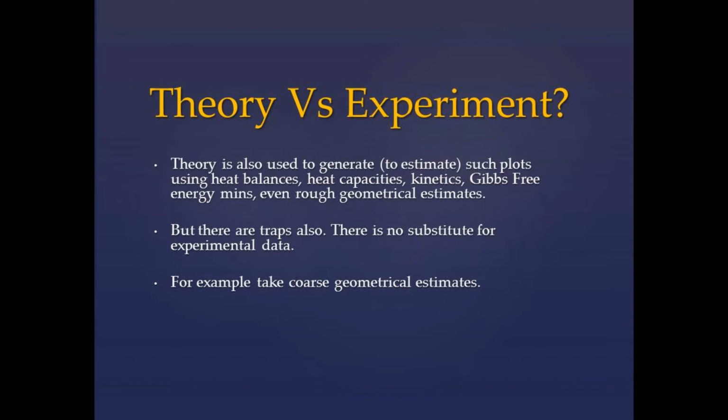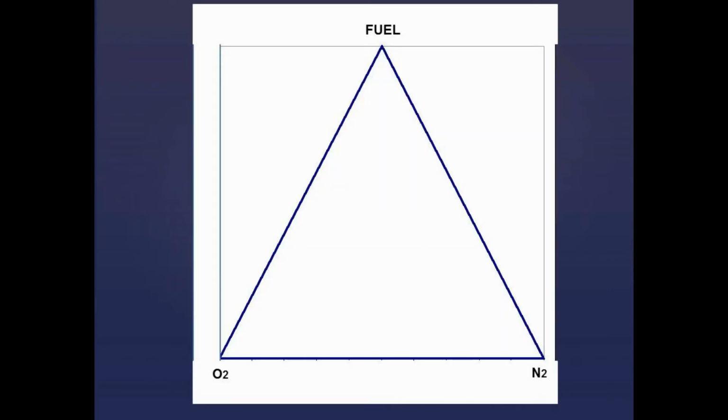A typical method of ternary analysis, which I have seen used a number of times, and an example of which has been and may still be on the net, constructs a coarse ternary diagram. I have seen this method used in practice in industry and do not disparage it. In this coarse approach, the pure constituents are at the apexes of the ternary graph. If published in the literature, one then plots the upper and lower fire limits on the fuel-oxygen or fuel-air axis as shown here.